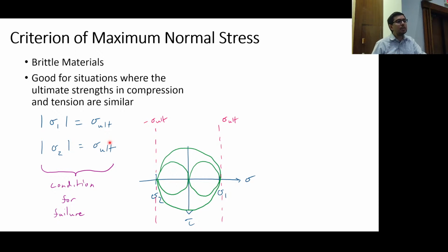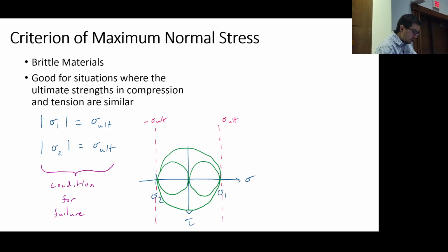Another thing that happens when you deal with these brittle materials is that you typically think more about the ultimate strength instead of the yield strength. Because do they yield? Not really. They just fracture and crack. So that is often called the ultimate compressive strength. I'll just put a little note here: we often think of this as an ultimate strength.